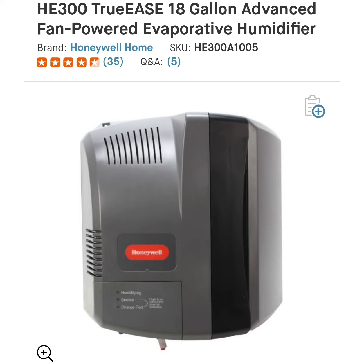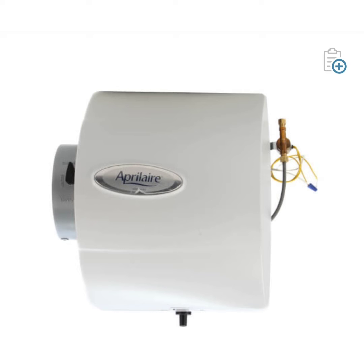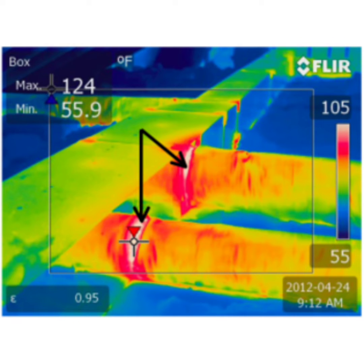That really isn't a lot of water that we're adding to the house. Even the economical humidifier models claim to be able to add 17 to 18 gallons per day. So a 5-gallon load doesn't seem to be a whole lot, but there are other factors to consider. Duct leakage is a huge source of infiltration because it's pressure-driven infiltration. Every time the blower comes on, if you've got leaks in your return duct, you are sucking in a large quantity of dry, cold, unfiltered, uncontrolled, unconditioned air, and that has to be accounted for also.